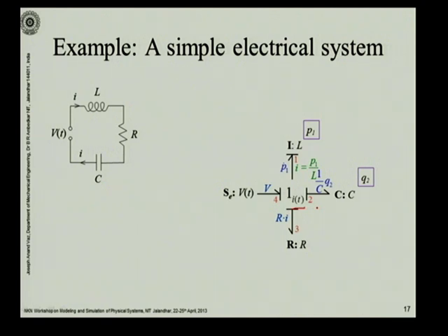And if you consider it as a linear inductance, you have P1 upon L. So this is the same inductance in all these bonds. And in this diagram, you made use of the same elements. They had different connotations in different energy domains, but each of them had an effort and a flow, and you are able to represent them.